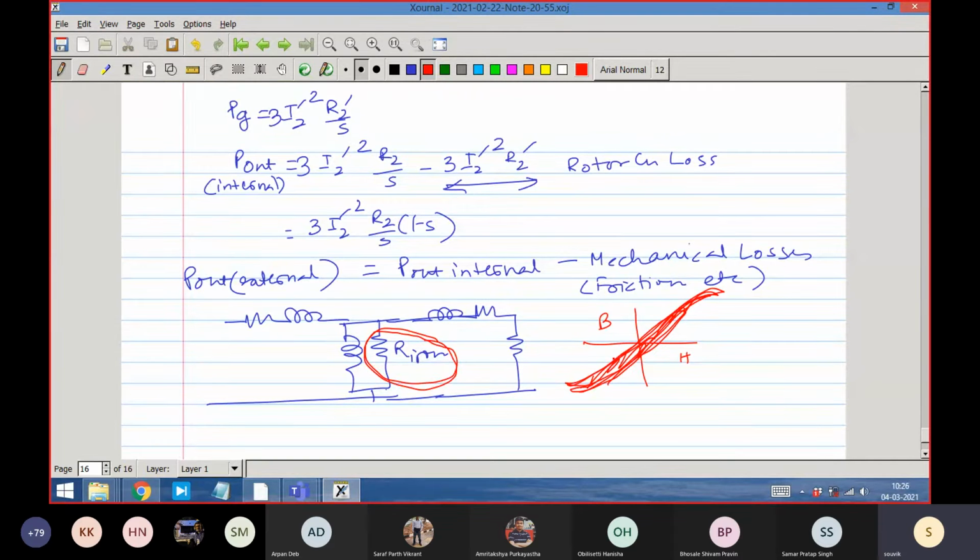That change is occurring because the magnetic field is rotating, and the stator iron is stationary. So through the stator iron, you will see north pole, south pole excursions going on at the same rate as the synchronous speed of the magnetic field.